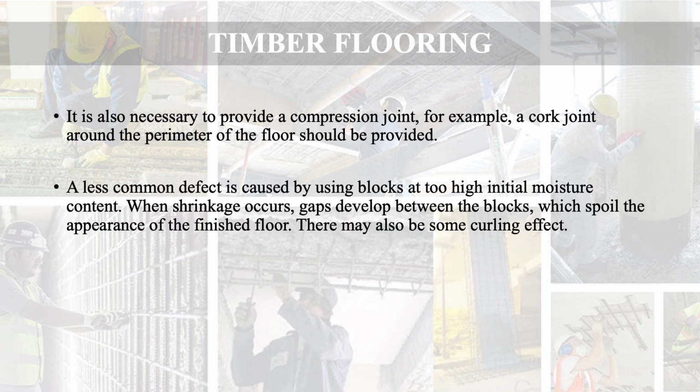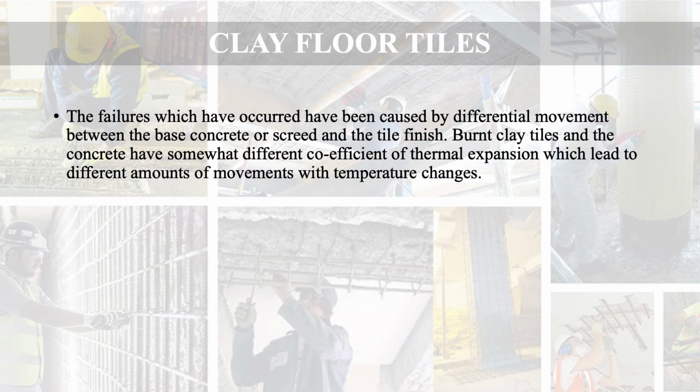A less common defect is caused by using blocks at too high an initial moisture content. When shrinkage occurs, gaps develop between the blocks which spoil the appearance of the finished floor. There may also be some curling effect. Now we move to clay floor tiles.